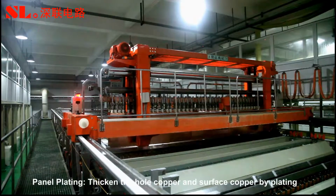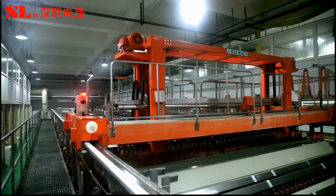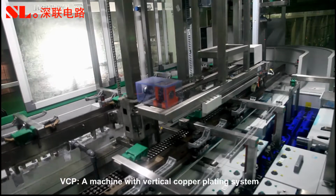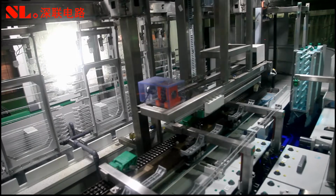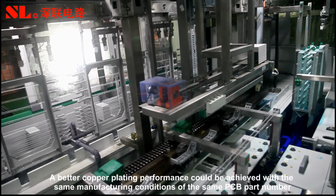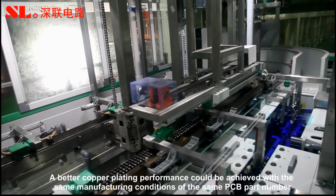Panel plating. Thicken the whole copper and surface copper by plating. VCP. A machine with vertical copper plating system. A better copper plating performance could be achieved with the same manufacturing conditions of the same PCB part number.